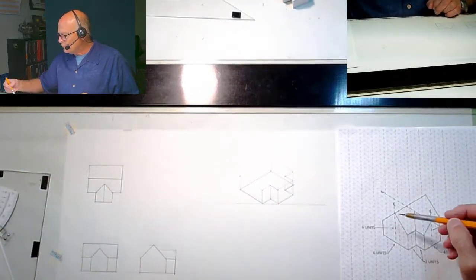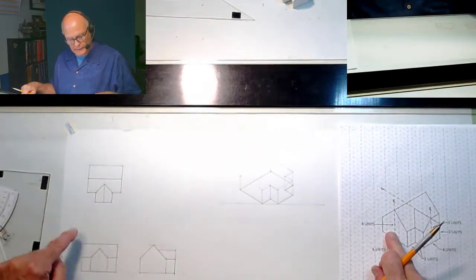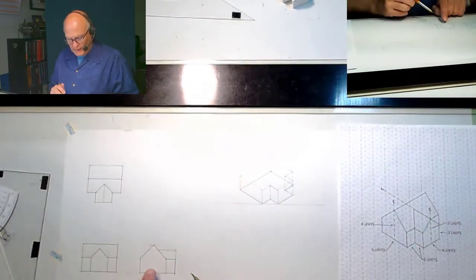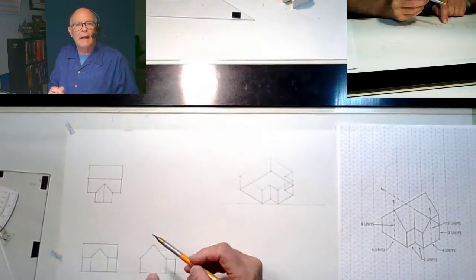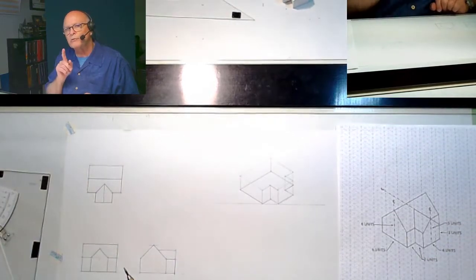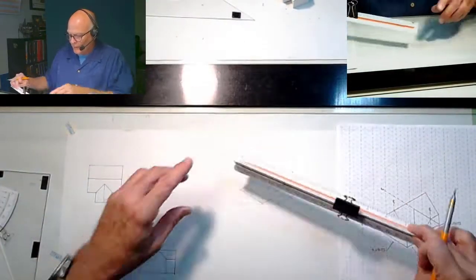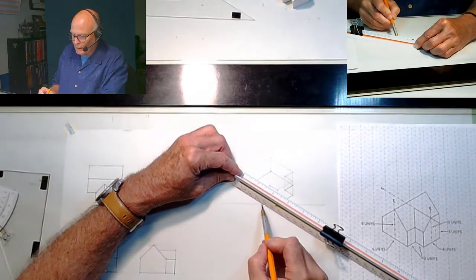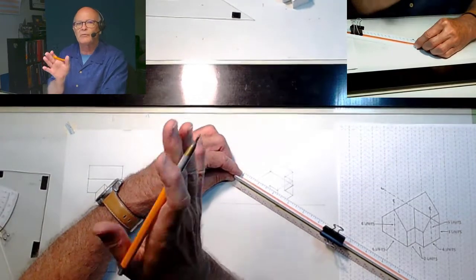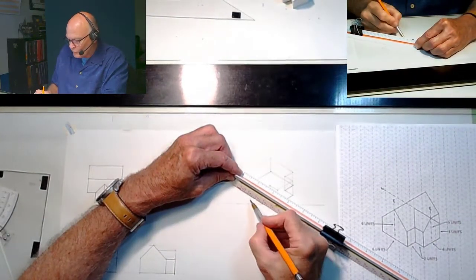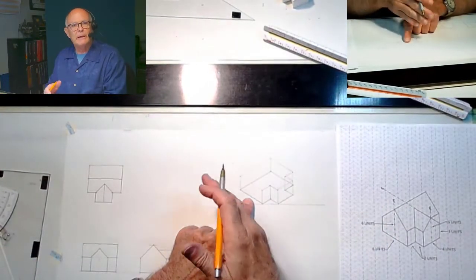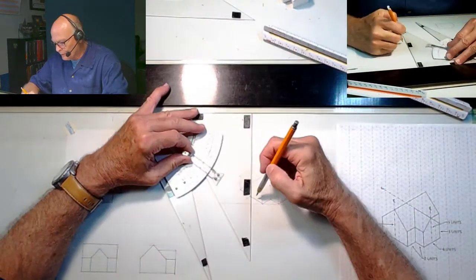So as a result, referring back to here and to here, we know that at the side view of this, let's start with this point, that this was in the middle, and we could project up 45 degrees to make that work. We can't do the 45 anymore, but we can still project to the middle. So, having said that, we're going to come to the middle of this drawing right here, and we know that it's 6, and the center point's going to give us 3 on one side and 3 on the other. So we're simply going to mark the point where it's in the middle, that 3-unit measurement. And we're going to extend it up.